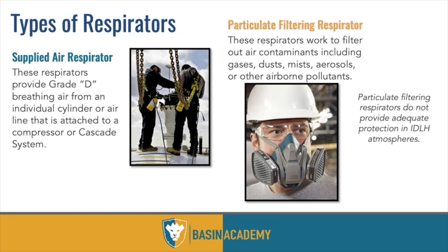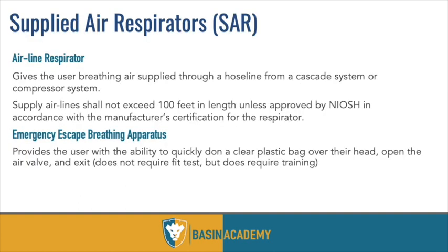We're very familiar with these now over the last few years, but this is the type of respirator that's going to filter it out for you. Supplied air respirators are the only type of respirators that are approved for H2S over 2 parts per million. So basically at any level that matters to us at all. And so we need to have our own air supply that's being fed to us. There are different ways that exist for us to get that air.